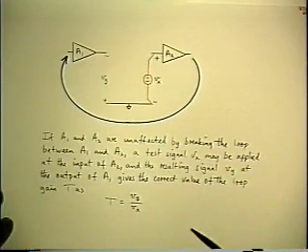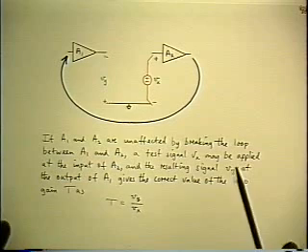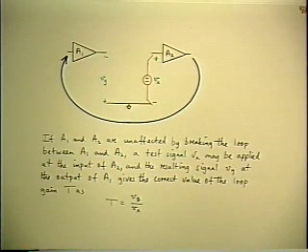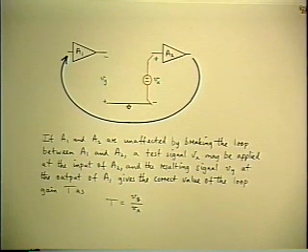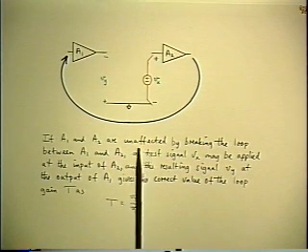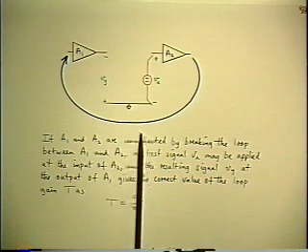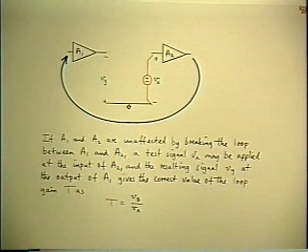Now, that's the first main point to make about calculating loop gain. The main thing is we've shifted the selection of the point to break the loop in order to find a place where we avoid upsetting the loading. And that's possible because it's only the T we need, and we don't need to know the A separately.